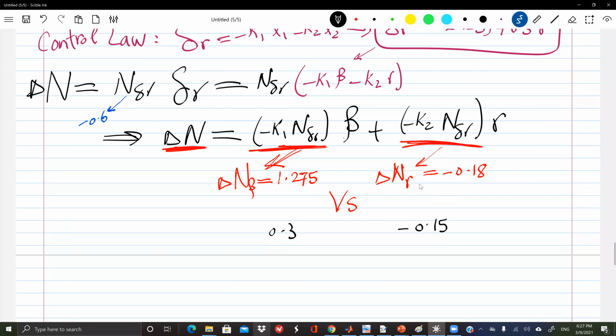The same here, my yaw damping. It was negative 0.15. Now I added in addition, so the total will be the addition of the two. So it's as if I'm adding 100% yaw damping. And these are just by feedback. These are virtual stiffness and virtual damping through feedback. These are the actual values due to the geometry of the airplane, the natural response without the interference of the pilot or autopilot. Any question about that?